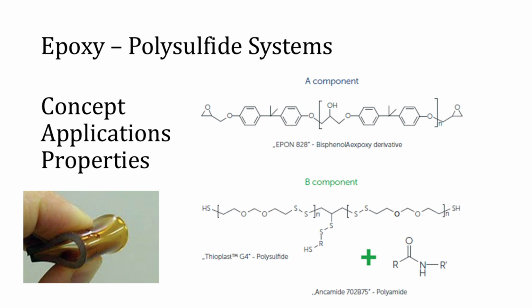In adhesives and sealant formulation, the epoxy resin usually remains the dominant component. The liquid polysulfides are added in varying ratios to tune the degree of flexibilization. Adding up to 58% of liquid polysulfide to amine or phenol formaldehyde epoxy resins results in increased flexibility, tensile strength, and impact resistance, while reducing brittleness and increasing elongation. This synergy allows manufacturers to create epoxy systems with a balanced combination of toughness and flexibility suited for demanding industrial applications.